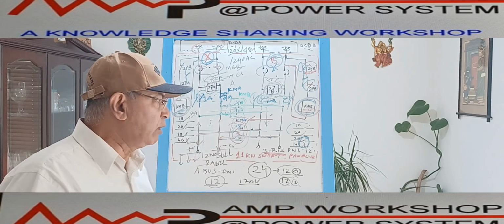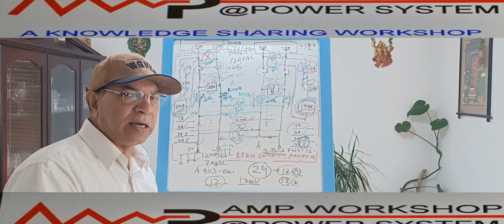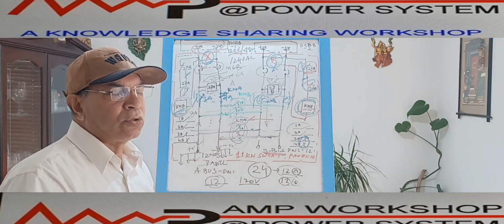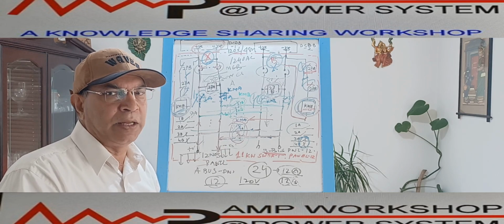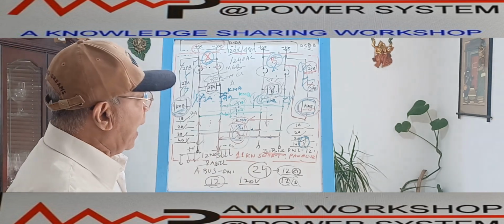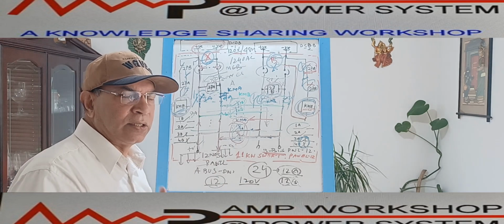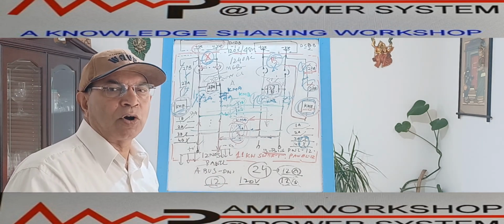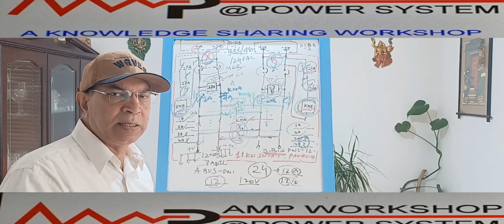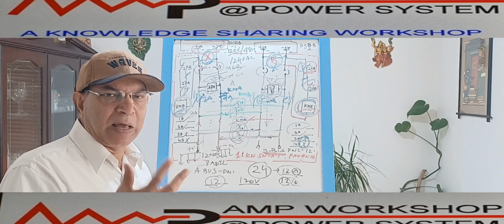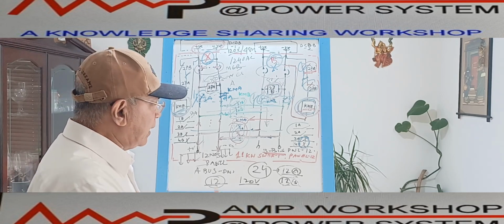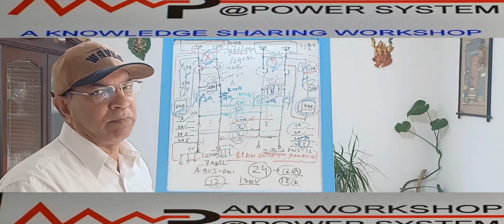We have to go through the synchronization of these two supplies, which we discussed in the case of the main power supply. But for the auxiliary power supply, which is a small amount, this type of synchronization is not very practical and not economical. That's why in this case we do not consider it. AC power, as we discussed in the case of switchgear, is used for all the auxiliary power, like the space heater, lamp inside the panel, indication lamps, tube light, plug socket. You can wait for 10 minutes, that is no issue. So in that case, this changeover scheme is absolutely fine for the AC supply.